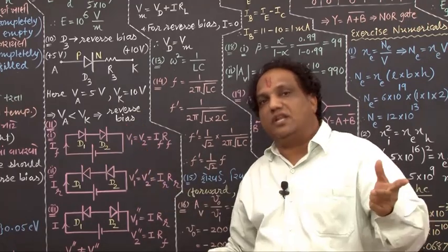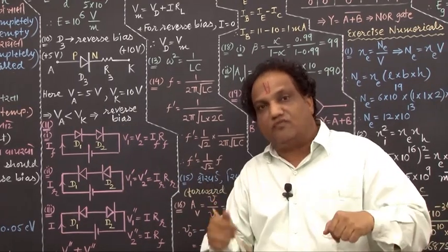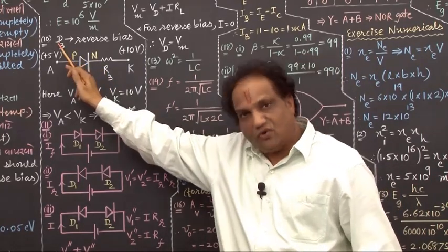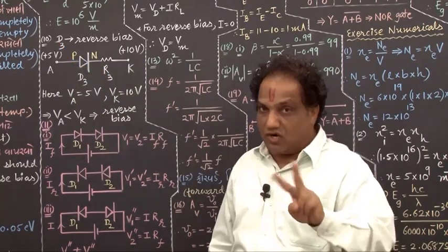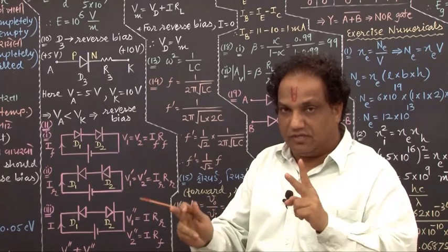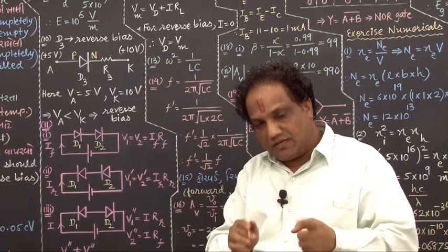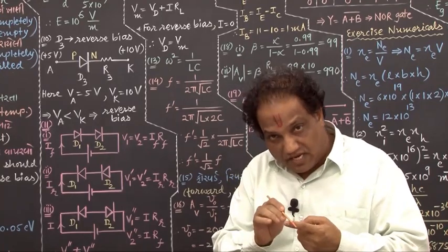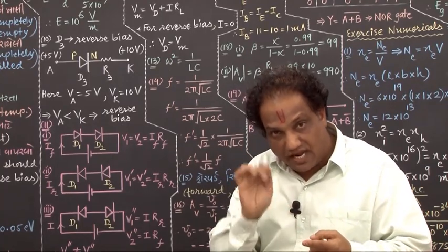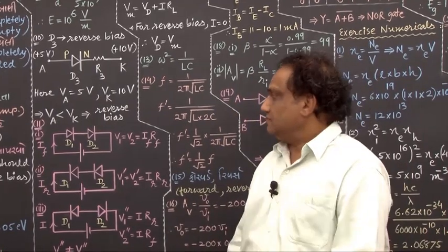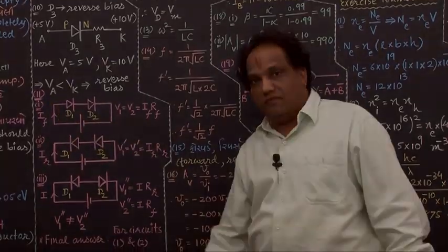Okay, remaining 3 are in forward bias. We are asked to find out that diode which has reverse bias. It is none but diode D3. Okay, they may change the order, they may change the symbol. So just be very careful. Try to understand. The diode which has reverse bias must be having low potential at anode and high potential at cathode. Okay, fine. Now read number 11.